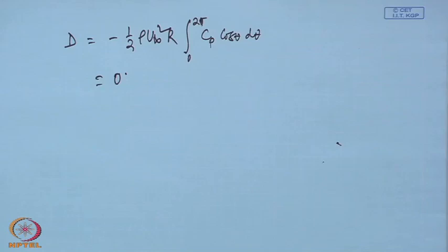And not only that, since a circle or cylinder has such a symmetry that even if your flow direction changes, the body is still symmetric. There are certain cases where if your flow direction changes, then the symmetry may be lost. So, consider the case of the Rankine oval. In that case, if the flow was in x direction only, it was symmetric, but if the flow direction made some angle with respect to the x axis, then it is no longer symmetric.